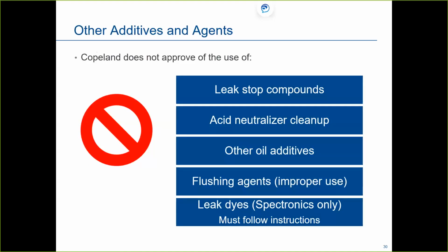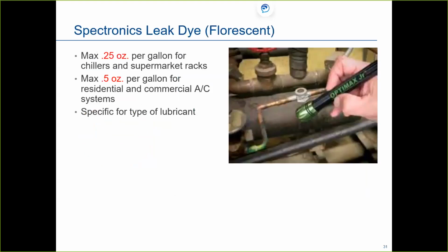If you don't, you're going to throw that refrigerant off, that saturated refrigerant in there. It won't be the same. If we check saturation with the refrigerant, vapor and liquid, we can go to our PT chart and look at what that should be at a certain temperature and pressure. But if we throw a bunch of chemicals in there, that's going to throw that off.